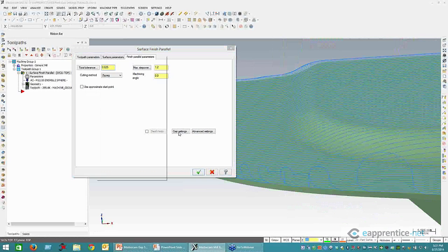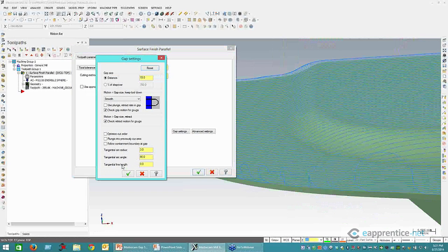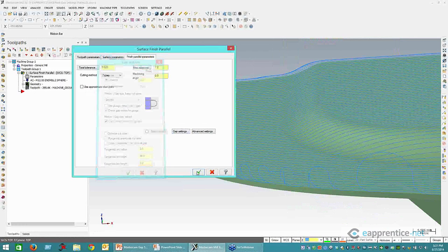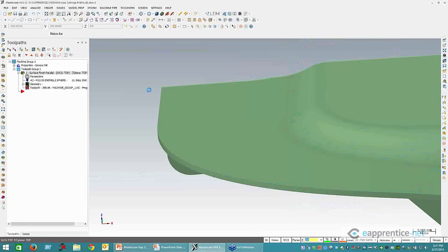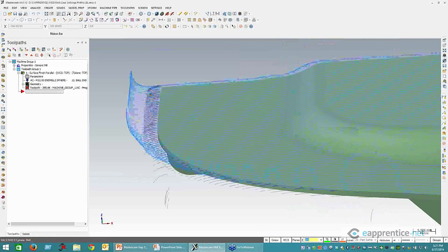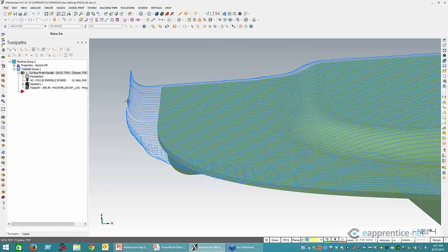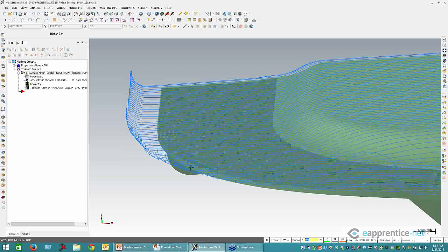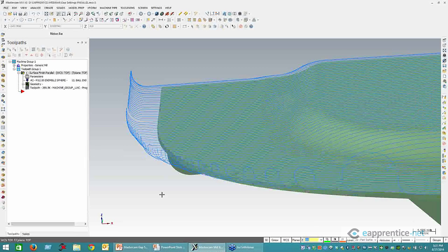And you can also combine the tangent line with the arc. So if I add a 3 millimeter tangent line with a 3 millimeter tangent arc, we can extend the motion off, arc up, move over in a smooth arc, and then arc back down onto the surface.